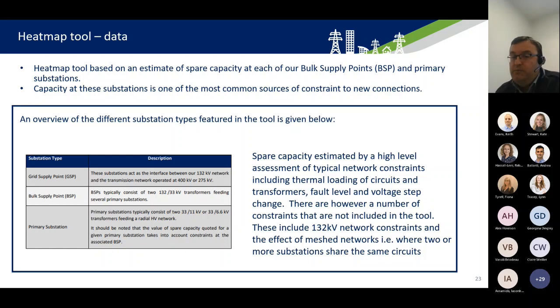The data is based on an estimate of spare capacity at each of our bulk supply and primary substations. This capacity is estimated through a very high-level assessment of typical network constraints, including thermal loading of circuits, plant and fault levels, voltage step conditions, and so on.